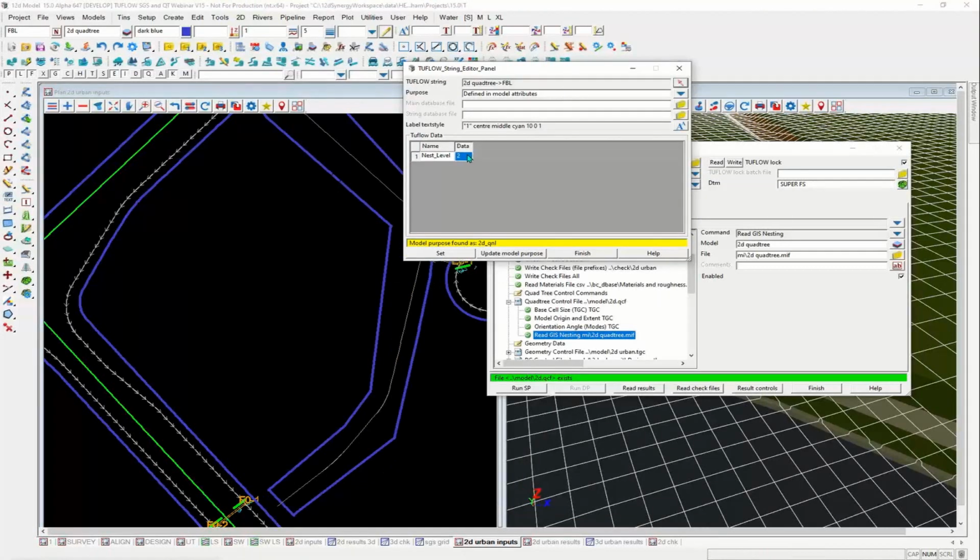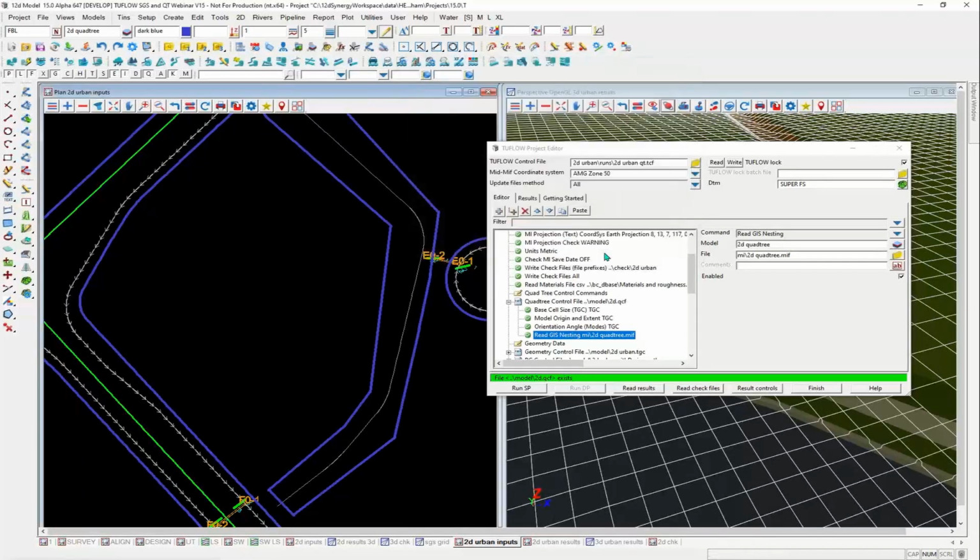And then we come in here and decide the nesting level. Now, we used a 2 for the roadways. If I wanted a lower one, I could put in a 3 inside there. And then, as Chris mentioned, it would go straight from the level 1 outside here, straight into the level 3. So it's got that automatic refinement if it's needed as well. So hopefully that answers your question. Essentially, that's all there is to putting in a refinement polygon.